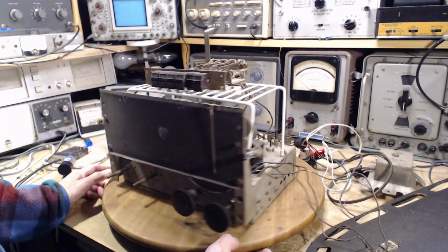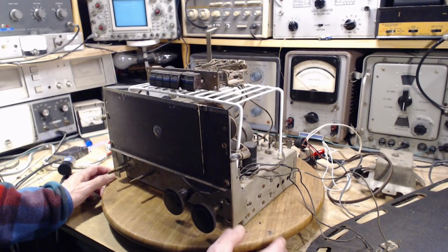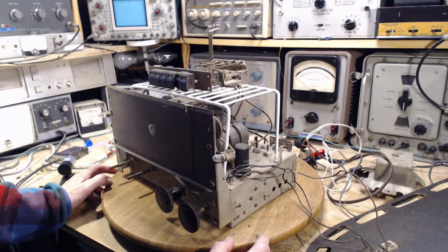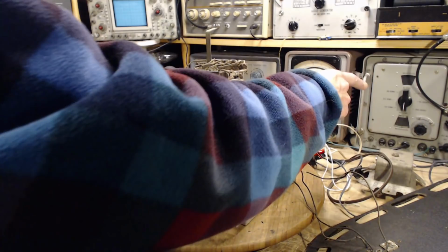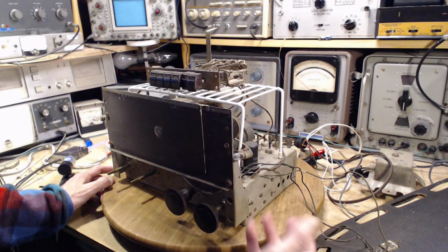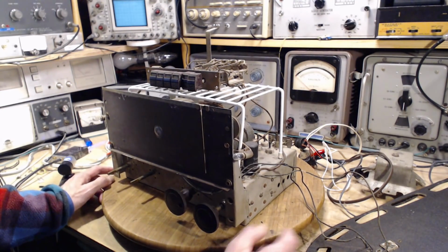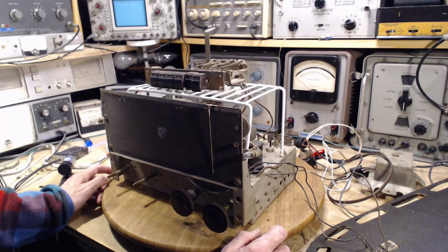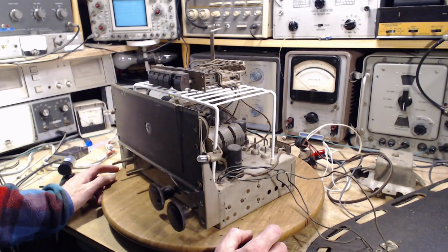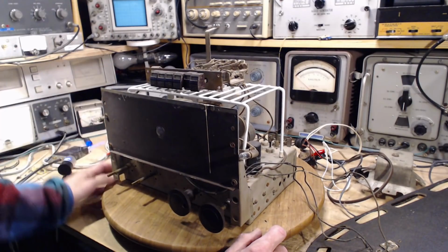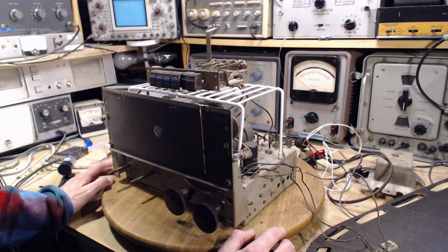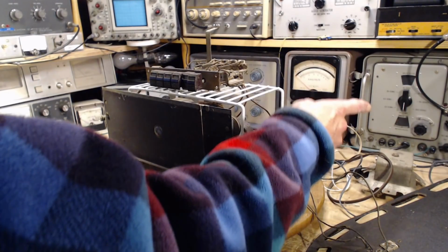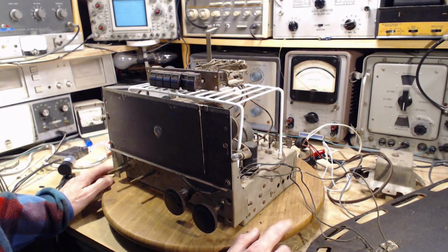I don't want to be tuning in radio stations while I'm doing this, simply because the radio is pretty weak and I don't have any control over the radio station. So I think what I'll do is I'll fire a signal into the radio using my signal generator here. And then we can listen to the output, or I can even put it on the oscilloscope, and we can look for the kind of distortion that's happening there. And then as we make changes, change a capacitor, change the tube, whatever it is, we can hear and see the variation. That's assuming we can hear the distortion with just a simple signal coming out of this signal generator. We can certainly see it if it exists. We can see it on the scope.